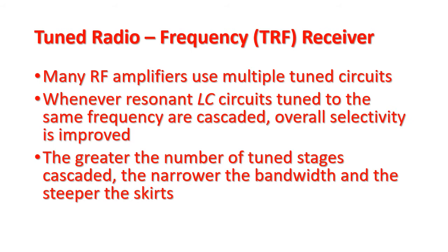Tuned radio frequency receiver. Many RF amplifiers use multiple tuned circuits. Whenever resonant LC circuits tuned to the same frequency are cascaded, overall selectivity is improved. The greater the number of tuned stages cascaded, the narrower the bandwidth and the steeper the skirts.